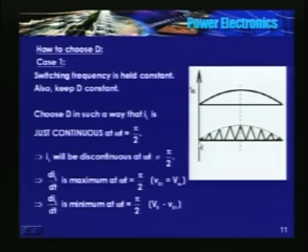See, the peak value of the current will follow a sinusoid, because the switch is closed for a fixed duration. VO1 is proportional to the instantaneous value of the sinusoid. So therefore the peak value of current is proportional to VO1 itself.